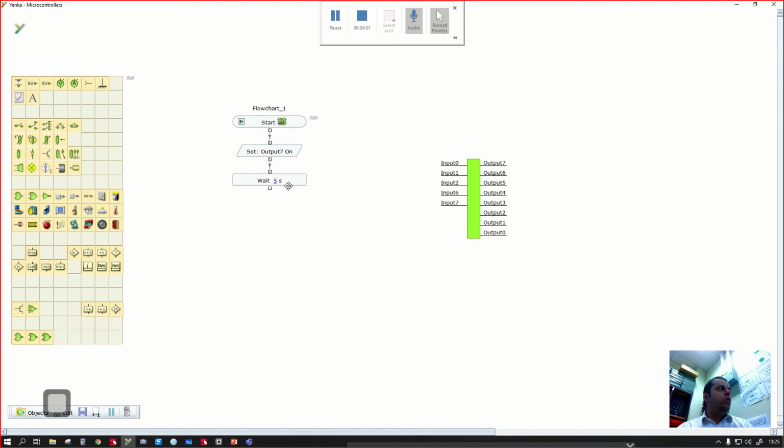We will use delays quite often with microcontrollers because it's one of the principal ways that we can problem solve, where we can identify if the microcontroller is doing what we need it to do. As I've mentioned before, microcontrollers are super fast. They'll carry out controls once every 4 microseconds in this case, in the real world. If it's doing something wrong, chances are we wouldn't see it doing something wrong. So in order to slow it down, sometimes we put delays in.